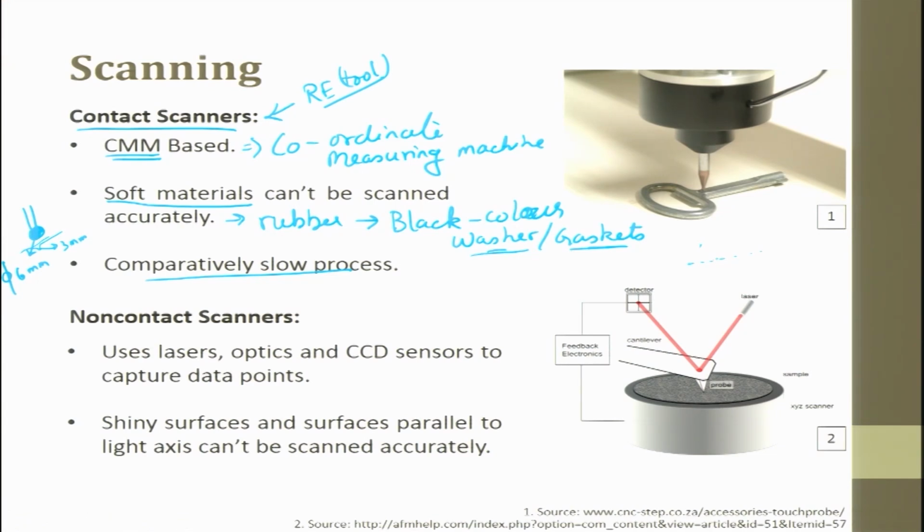Okay. So one way of scanning the workpiece and getting the data is through the contact technique. The other way is through the non-contact technique. The moment you say non-contact, light is the one major tool which comes in handy. Again, in light there are two kinds, one is called coherent light and the other is called white light. The moment you say coherent, we always use laser, and the moment we say white light, you put a prism, take a particular wavelength and start using it.